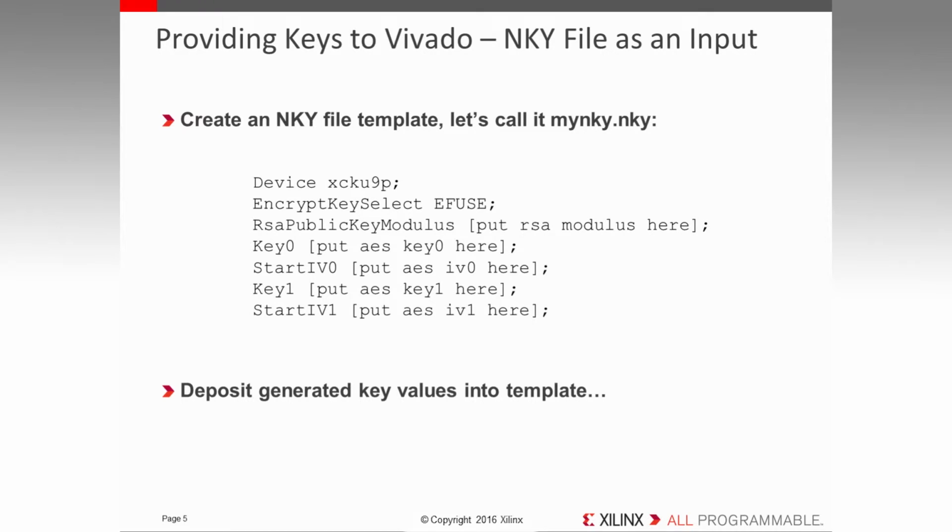In the Lock Before You Leave video, I showed the specification of the single AES key interactively through Vivado. This set a property in the XDC file, and during write bitstream, an NKY file was generated. Now that we have many more keys, interactive specification is not practical, but we can capture all the key values in an NKY file and use that as an input to write bitstream.